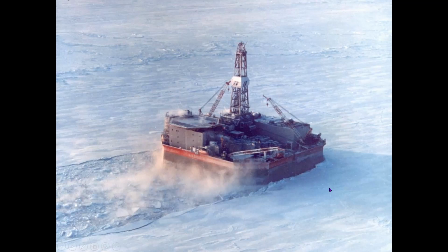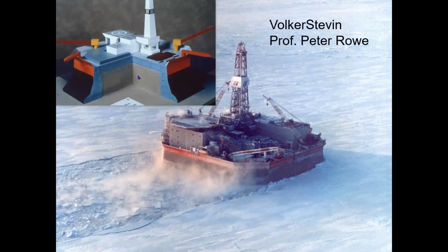And what happens when the ice moves past? It's coming past at about 1 knot. It crushes on the front of the platform. And this crushing can go on for hours, and it vibrates the platform. The largest accelerations we measured were in excess of 11 G, and we sustained that for 15 minutes. Now, how do we deal with these large loads on a platform? Well, you can't do it with jacket legs. The platform is actually a large shear box, and it's full of sand.